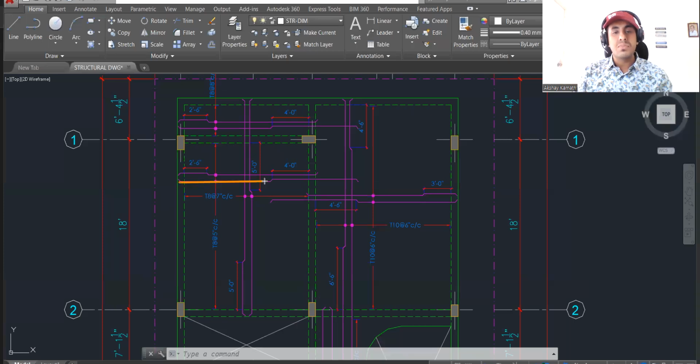That is why we usually provide this bar and give a crank, which means it will go to the top, and this top will continue. You can stop here also. Then if you start again for this particular slab, you have to start like this only. Rather than giving two different bars, why don't you continue the same bar? So we'll just continue this particular bar in this way.